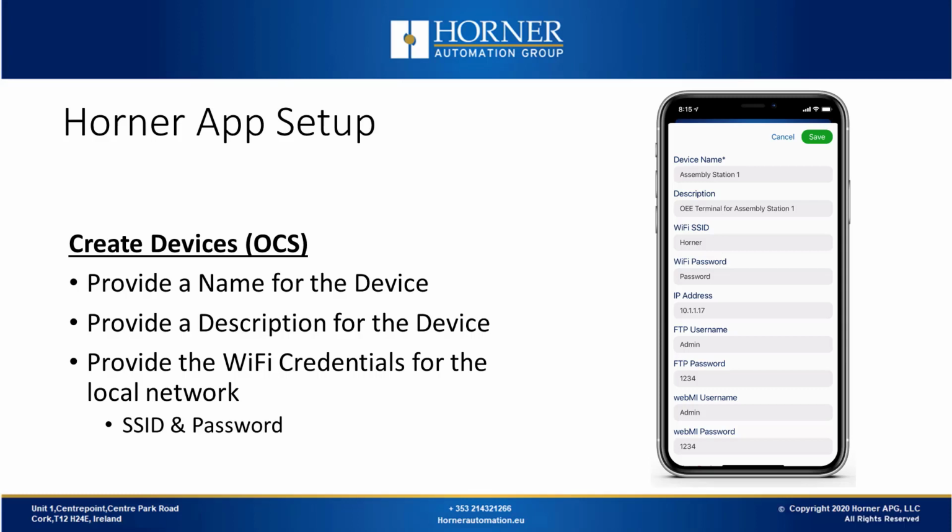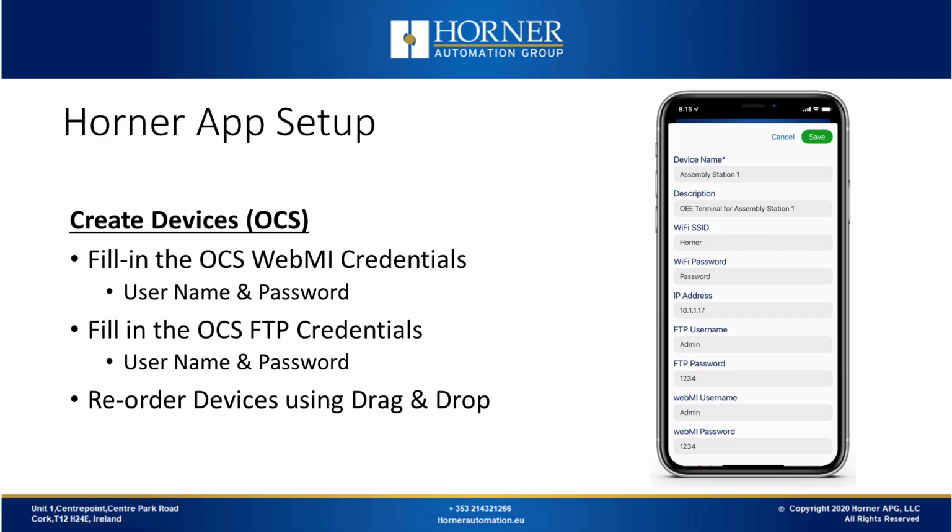Next is IP address. This must be entered as every OCS will have an IP address, which is used to access the controller for WebMI and FTP. Next is FTP. If you want to access this OCS using File Transfer Protocol to be able to see all the files that are on the microSD drive, then you'll need to fill in the FTP username and password that provides access. Finally, there's WebMI. If you want to access this OCS using WebMI, you'll need to enter the WebMI username and password.